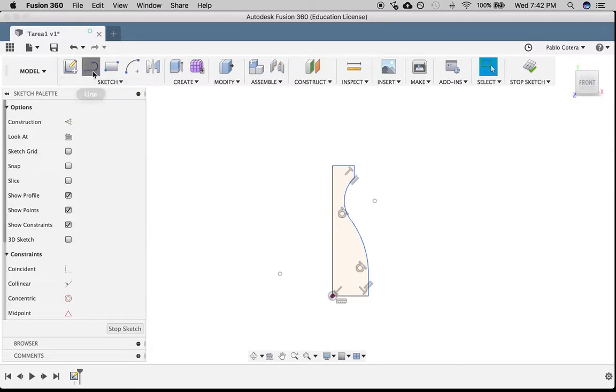Okay, so I'll just draw again a line here about 2 centimeters, or in this case 20 millimeters, so I can just write it down. As you can see here, I haven't clicked the line yet, so it's just a horizontal line, and I click 20 and then enter, and that creates a 20 millimeter or 2 centimeter line. Okay, so far so good.